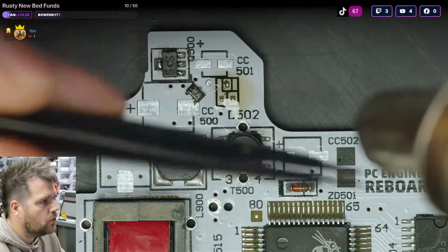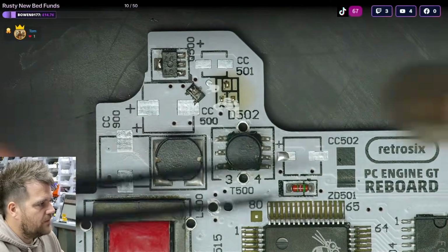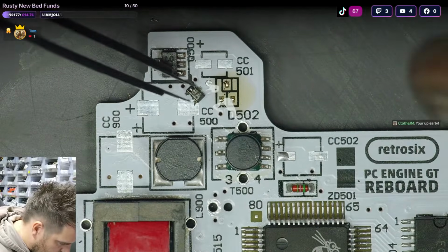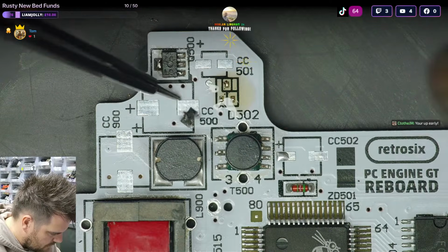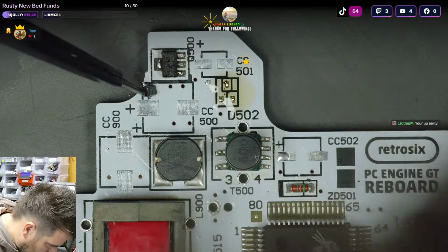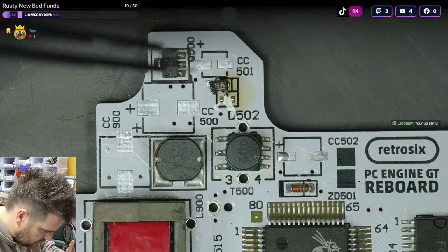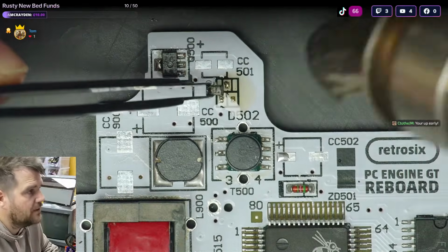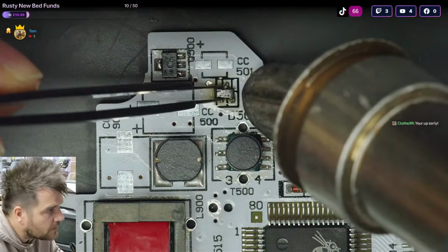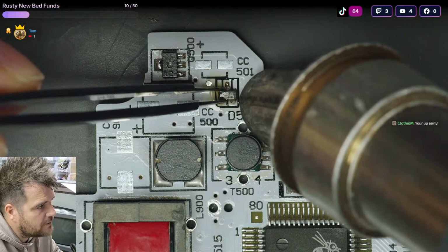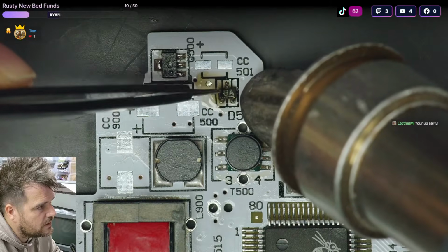And if it wasn't for the fact it says D502 here, we might have been tricked into thinking that was a transistor, but I did notice that it showed up as a 0. Afterwards I noticed it showed up as 0 current passing through the transistor, which was a hint that it wasn't a transistor as well. Might have been a quicker way to identify the diodes as well.